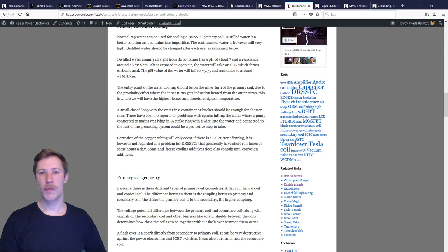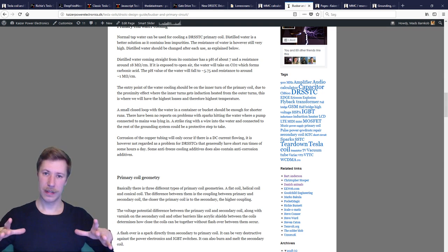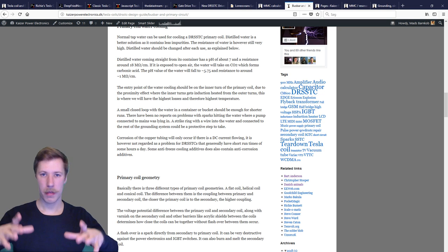So there is really no advantage gained by using the larger tube. This comes down to water cooling becoming a must when you get over maybe 1000, maybe 1500, 2000 amperes in your primary circuit. And important here is, of course, to water cool it from the inside and out, and this has to do with the proximity effect, or the induction heating effect, that the outer turns of your primary coil will heat the next turn, and these 2 turns will heat the 3rd turn.